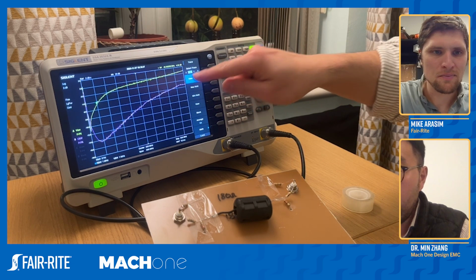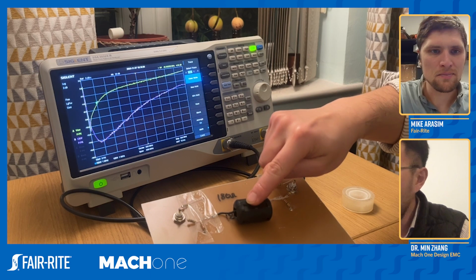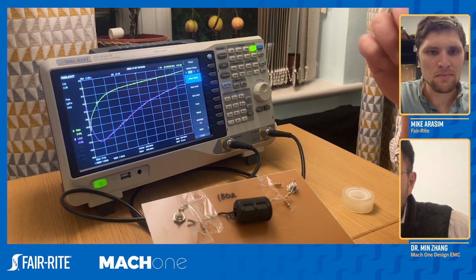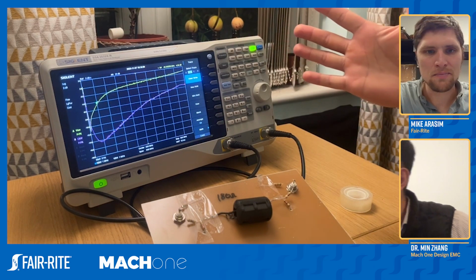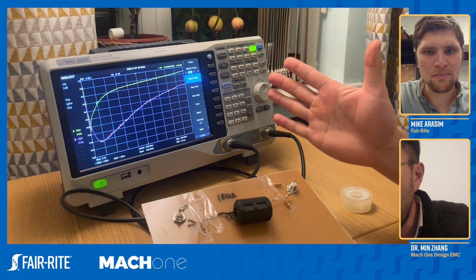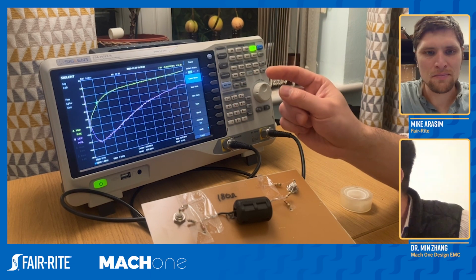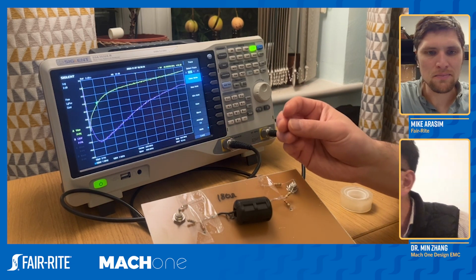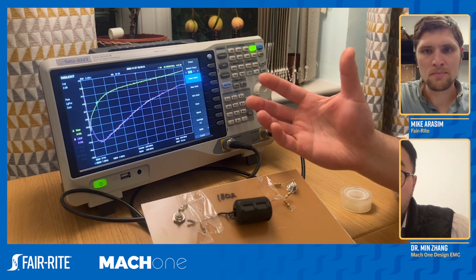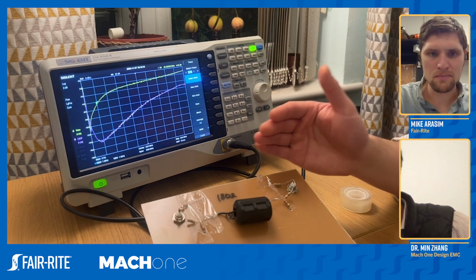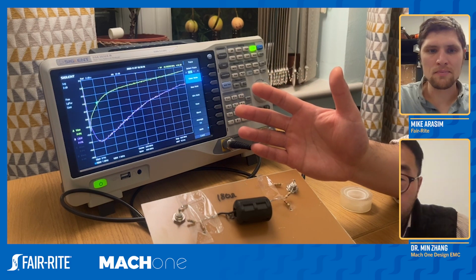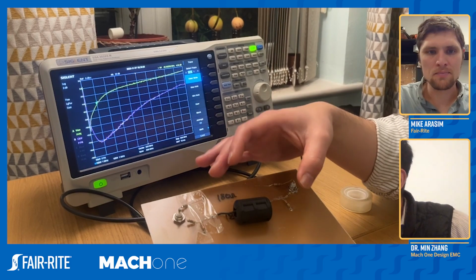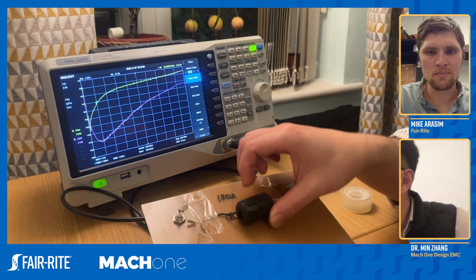It is worth mentioning that before I place the ferrite on this cable, I need to do a normalization first, for the exact reason that you just said. We are measuring the frequency, in this case, up to about 500 megahertz. Therefore, the wire length, being a few inches long, introduces about 60 to 80 nanohenry of inductance. You can work out that at 400 to 500 megahertz, its impedance actually dominates. So we definitely need to normalize that out.